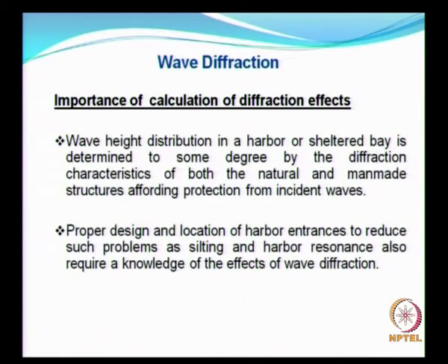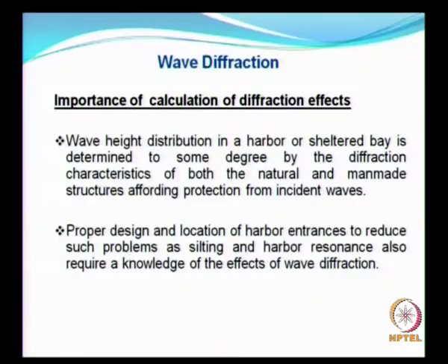There are several ways of aligning your breakwater. Please remember that the main purpose of providing a breakwater is to absorb, to be more specific, to dissipate incident wave energy, so that on the lee side of the breakwater you will have a calmer area.